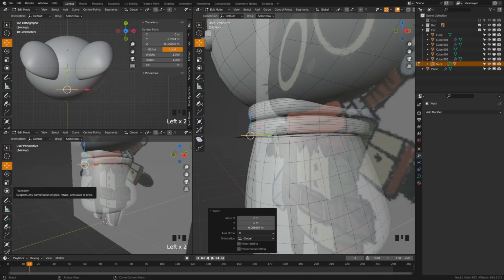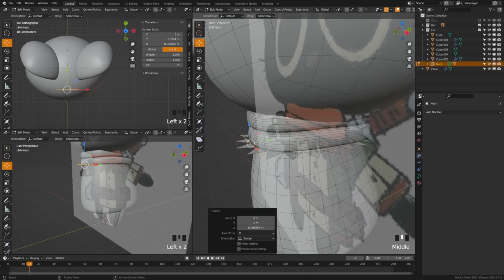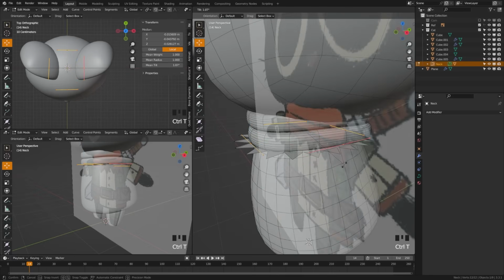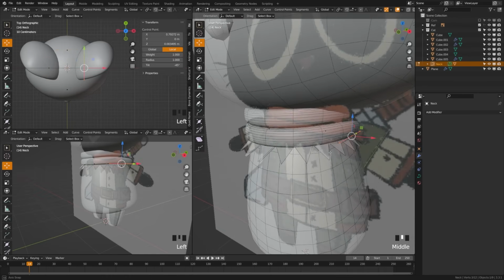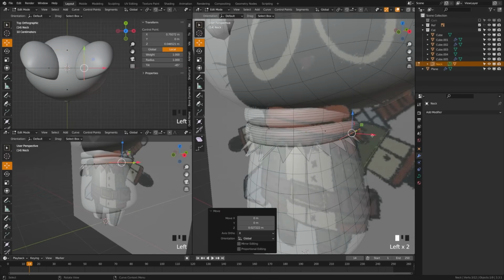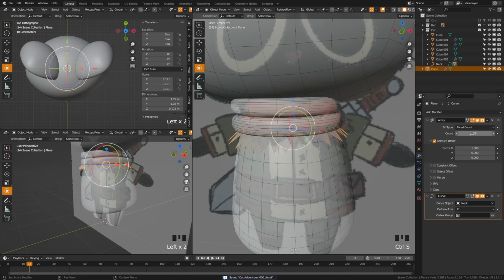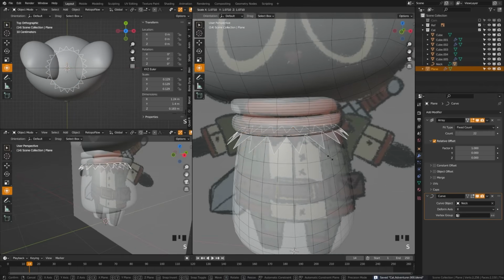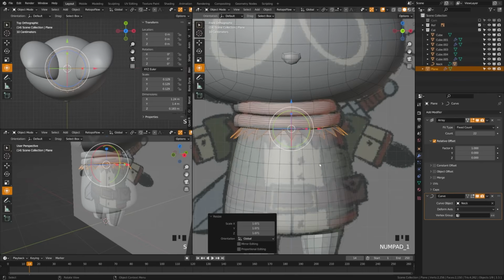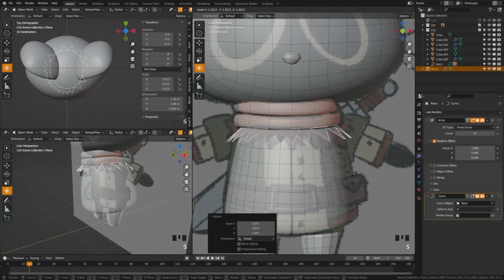Great. So now what we can go ahead and do is begin adjusting the size of these triangles and the angles. So if you grab all the points and hit Control-T, you can control the tilt. So you can see by grabbing all those points and hitting Control-T, I can move my mouse back and forth and tilt all those so they're kind of hanging down. Now let's go ahead and adjust the count of these triangles. You do that with the triangle selected, and then you can scale up and down on the triangle so that it kind of fits into position.